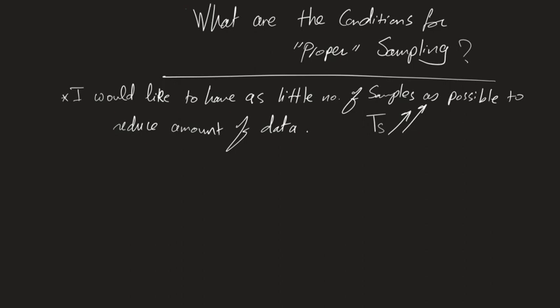Okay, nice. Well, what if I increase Ts and I end up with the whole signal, I take one sample? Where is the problem? Just for the whole duration of the signal, I take only one sample. Now imagine that I had a signal that looks like the wave that I drew previously, and I have another signal which is just a straight line. And I pick one location and I take a sample and that's it. And I give it to the computer. Now I want to process and get the original signal, right? After processing, how would I know if the original signal was the line or the curve that I drew or whatever, right? So that would tell me, intuitively, the more samples I take, the better I will be able to recover the original signal, right?